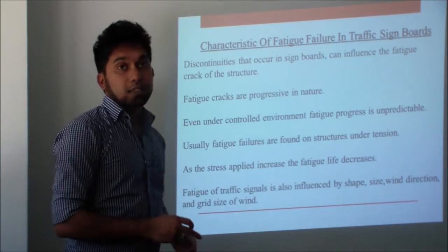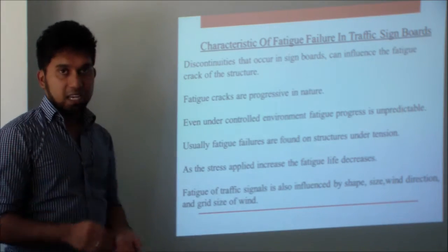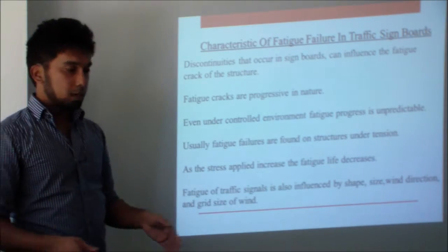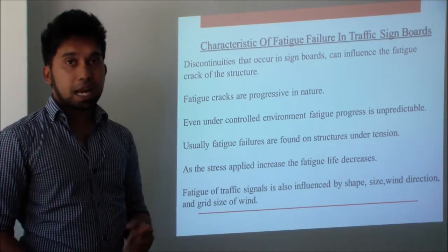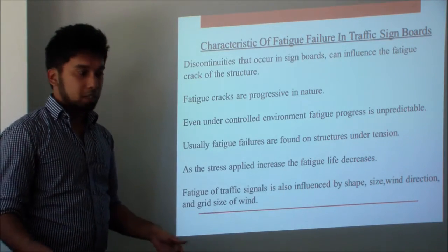As I said, fatigue cracks are progressive in nature. Once a crack is formed, it will progress in all directions, ultimately leading to the failure of the structure. So even under a controlled environment, the fatigue damage is unpredictable.